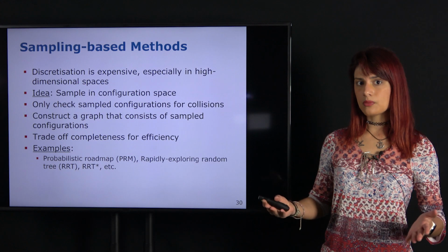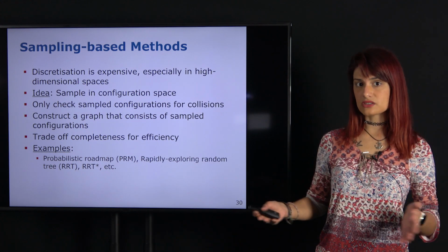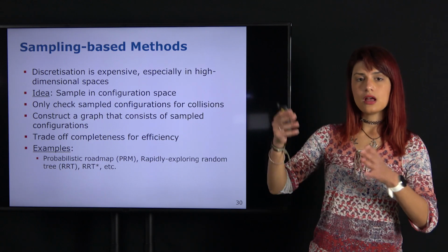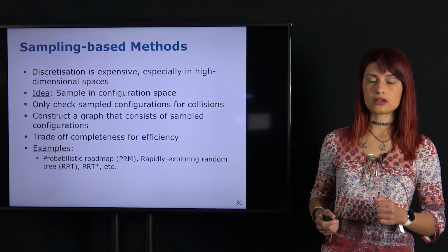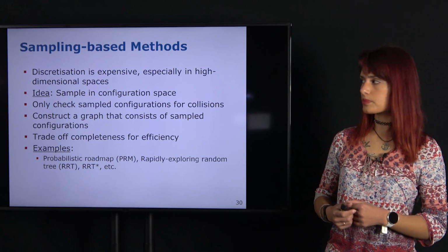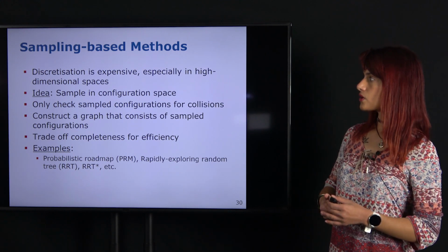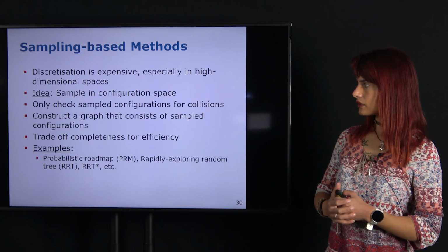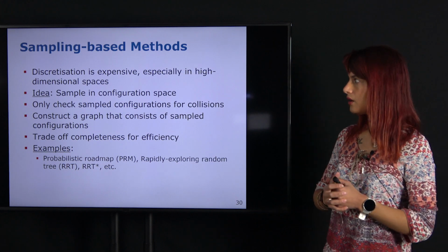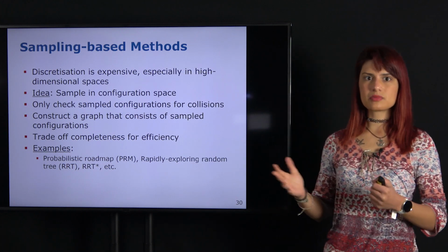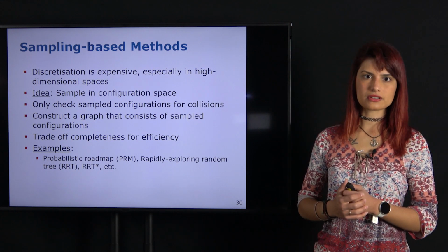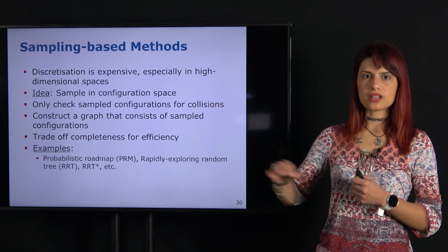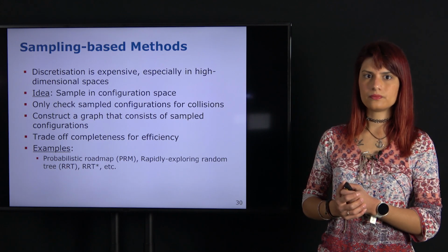Consider, for example, how much memory a grid that is in 2D occupies compared to one that is in 3D and has many cubes associated with the entire volume where the robot is operating. So sampling-based methods go around this by sampling. The insight is that collision checks and visibility checks are a fairly simple operation. We just connect 2 points and we check whether this constraint is satisfied, whether an obstacle is in between.